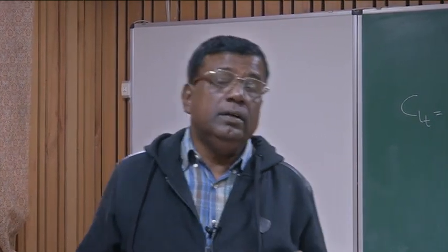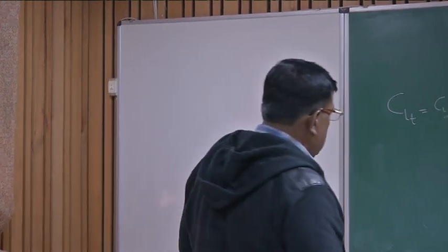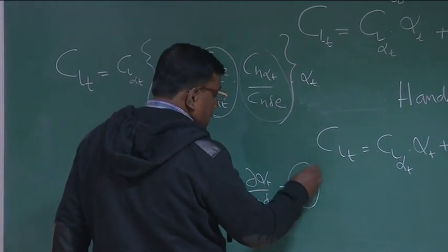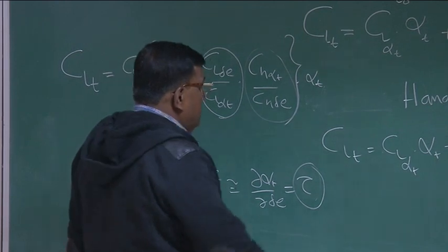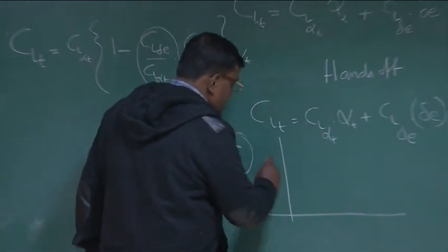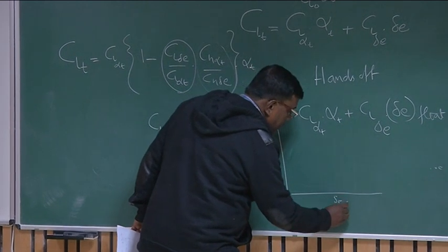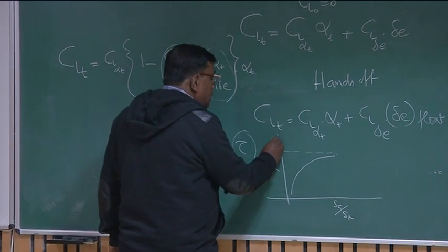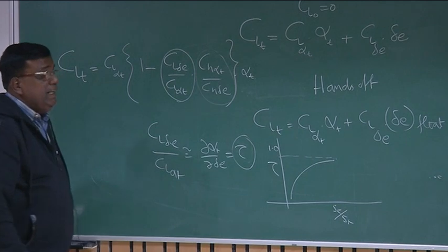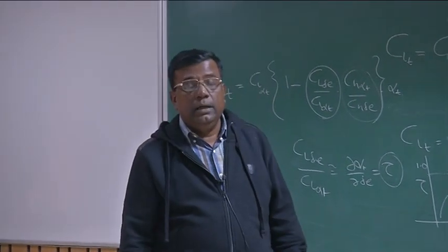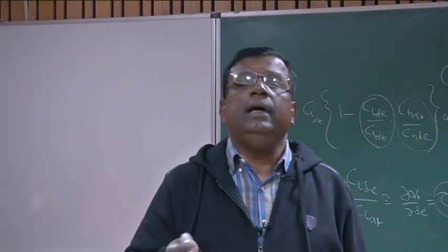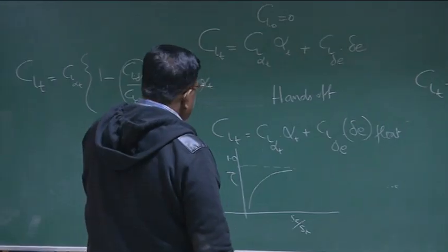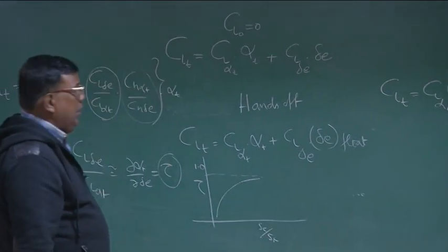It's a very, very important performance parameter in design in terms of tail performance parameter, and that is denoted as tau. And you will see that when you solve an example, this tau can be estimated through some empirical relation which goes as, I'll give you the right figure for this. It varies with AE by ST, that is elevator area to tail area, and typical value for most of the airplane lies between 0.4 to 0.6. That's a good enough value. Okay? This exact numbers we'll be using to do our numericals.